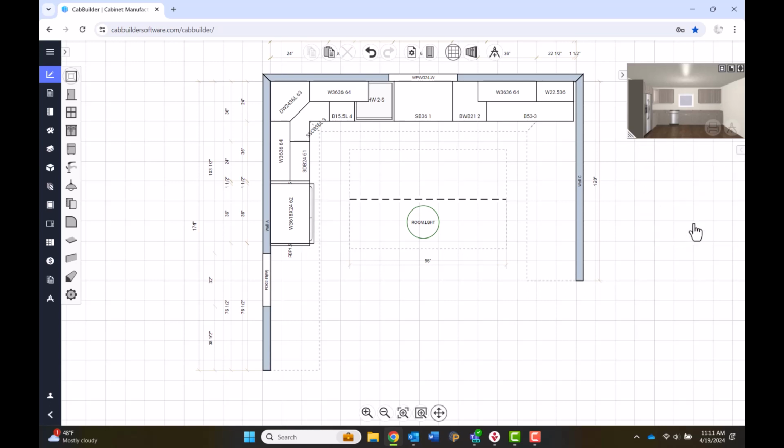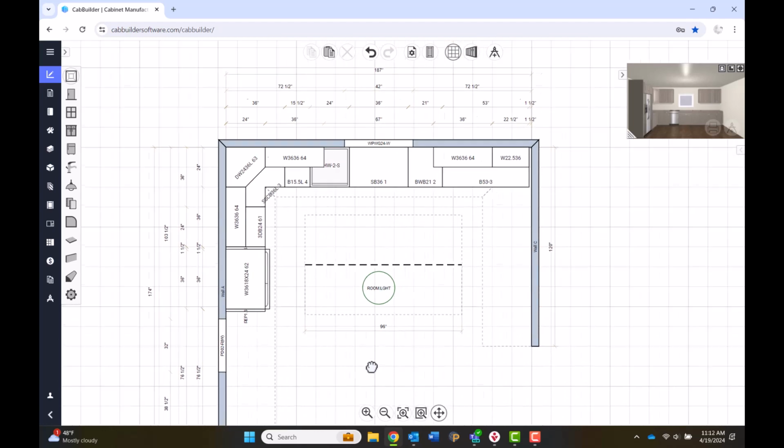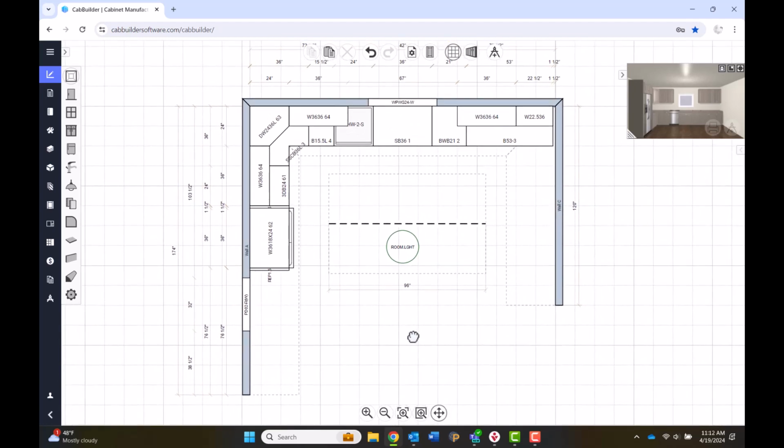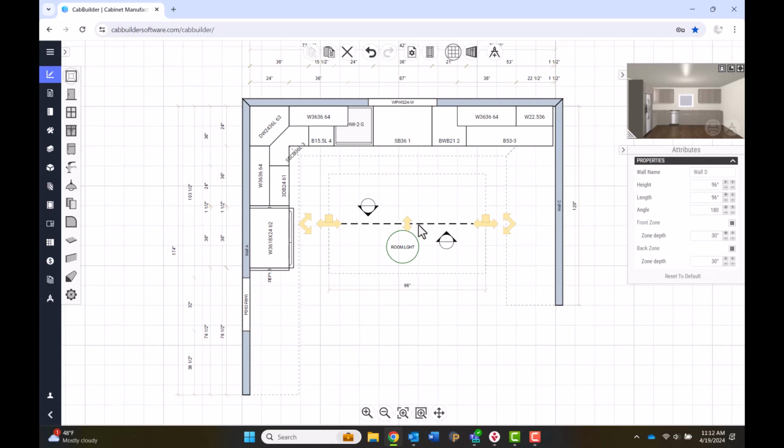After releasing the tool, your mouse may turn into the outline of a hand, indicating that the mouse is in pan mode. To return to mouse mode, click the cardinal direction icon below marked pan. If you need to move the construction line in or out from the opposing wall, left-click on the construction line to select. Then, left-click and hold the center wall handle and slide the C-line into a more appropriate location. Then release the mouse to secure.